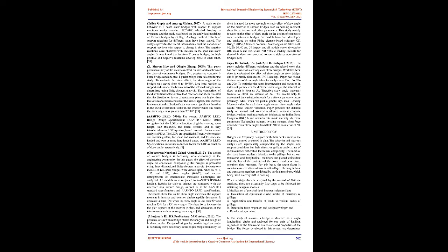3. OHBDC, Ontario, 1992. The Ontario Highway Bridge Design Code, OHBDC, Ontario 1992, accounts for longitudinal and transverse rigidities of bridges in addition to the girder spacing. However, the method is limited to simply supported and small skew angle bridges. Several researchers have investigated the load stresses in skew composite bridges, presenting empirical formulae for moment distribution factors for bridges subjected to AASHTO truck loading.